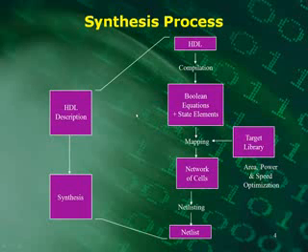So let's look at the actual synthesis process, where you take your HDL description and synthesize it. You start off with your HDL code, Verilog code. You're going to compile it with your tools, and that's going to produce an intermediate set of Boolean equations and state elements. Then it's going to run through a mapping process typically, where it's going to include your target library. Let's say you're using Altera, it's going to be the target library for that particular Altera device.